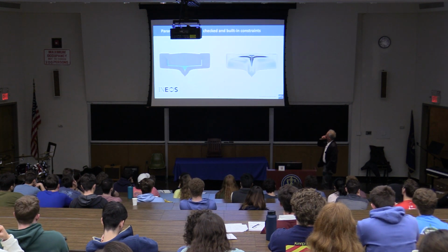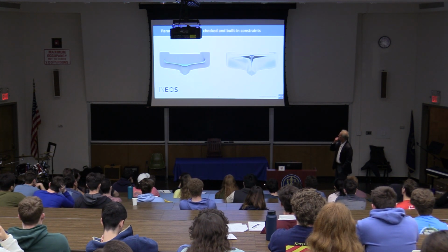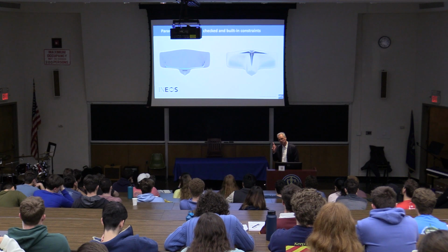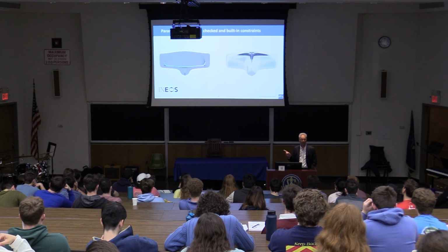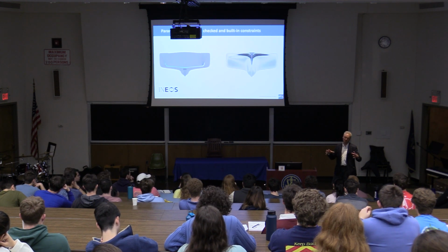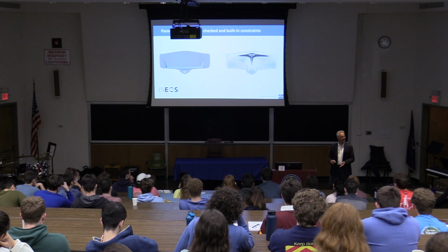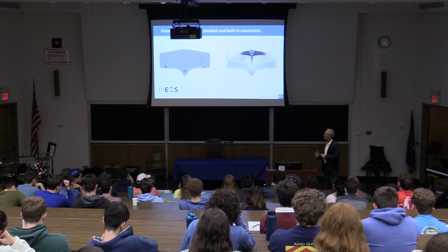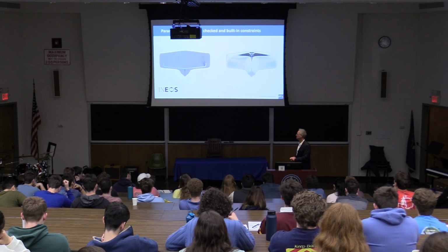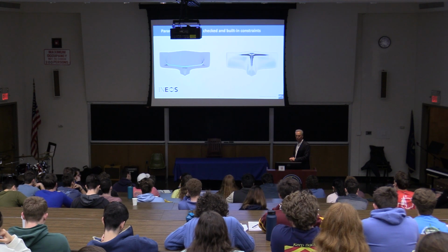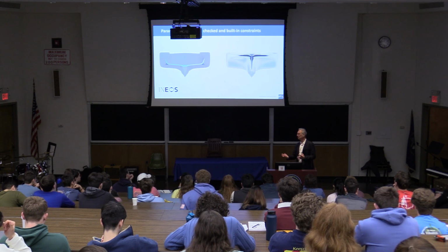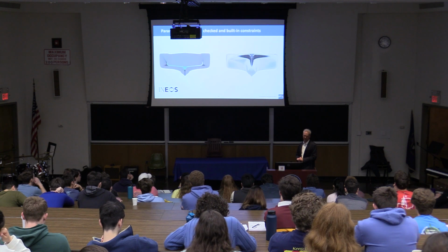All right, just another view on those Ineos hulls. Interestingly, Ineos Britannia decided, on the basis of simulation design, to go towards a completely different type of hull. Most hulls, including the one from the US, were as small as possible, while Ineos Britannia in the end came up with the largest hull. And their design thinking was coming from the simulation-driven design effort, and it would actually give you more control and more reduction of downwash and a certain advantage at lighter winds.